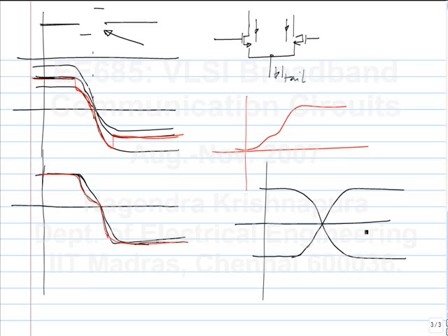What happens with the tail node capacitance is, this becomes smaller in magnitude here and larger in magnitude here, and the other one also becomes smaller in magnitude. Actually it does sum up to 0, right? Does it or does it not? If you look at the differential waveform, it looks symmetric, but you have to also keep in mind that this has a lot of approximations and things will not be exactly symmetric.